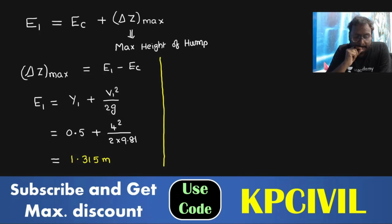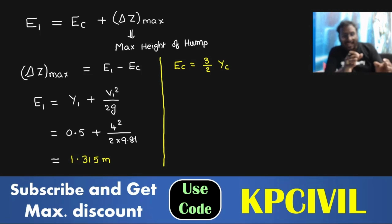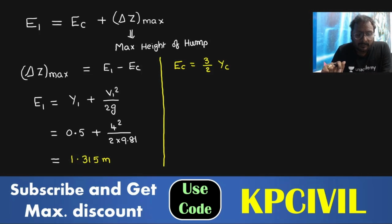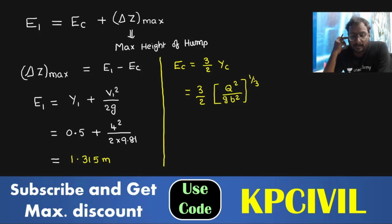If you want EC, what is the EC formula? EC, critical energy, is equal to 3 by 2 YC, critical depth. See, all the formulas are interlinked to one another. If you need critical energy, you need critical depth. If you need normal energy, you need normal flow depth. So for a wide rectangular channel, EC is equal to 3 by 2 YC. That formula we already solved in the previous question: 3 by 2 into Q square by G B square whole power 1 by 3. Substitute it now.